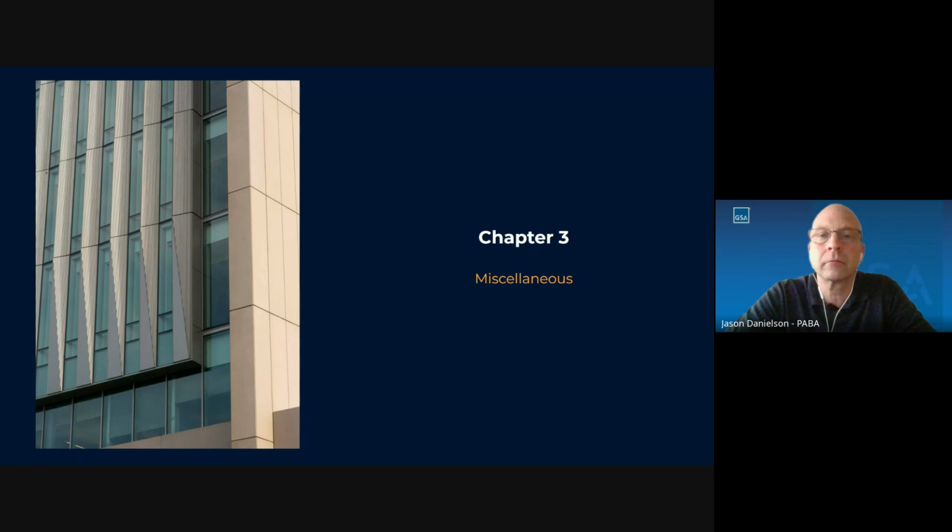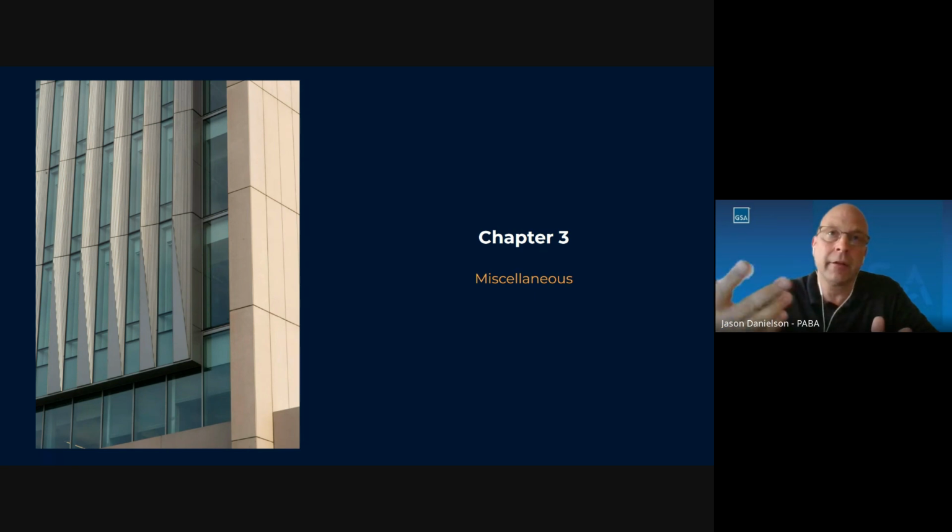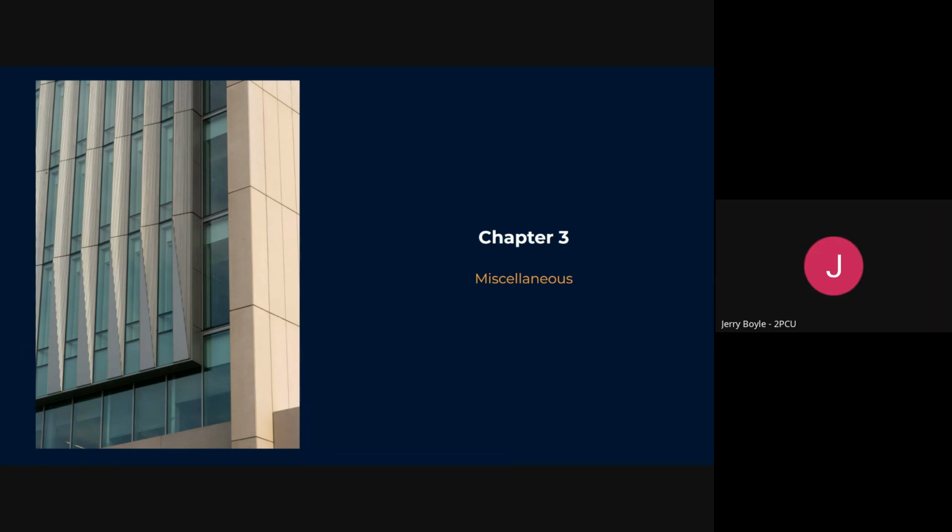Yeah. Well, and Jerry, you hit a few things. And so the DLR study, the NIB study also looked at increasing insulation. And we're actually finding that the insulation that we have right now, the 30% better than ASHRAE, that payback is questionable already. Now, going to even more insulation, the paybacks are not there, which is really kind of surprising to see. So it's really tightening. It's not to me, because I think it's the windows that's my problem. Is the insulation, the heat losses through my windows and not my roof. It's not going up the building, it's going out the building, because I always get another space between it. I got a mechanical space or something else with that.